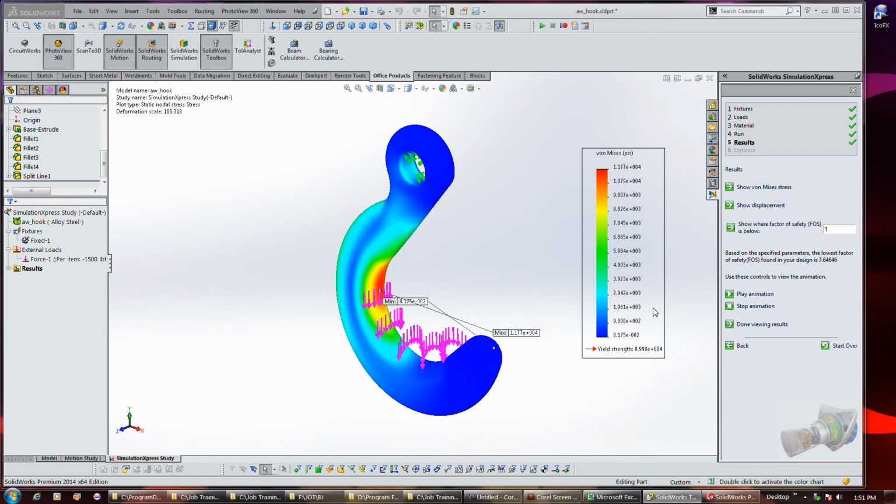And let's say the difference is small, like 7.6 versus almost the same. It's a small difference between the two, so it implies that the results are fairly accurate, because kicking it up to a much higher density mesh usually yields more accurate results. If there's a large variation, you start to wonder if there's something amiss.